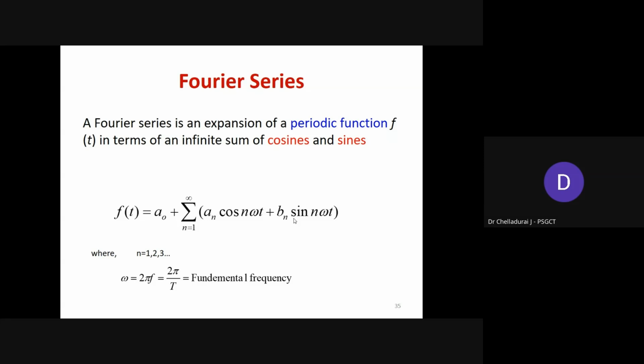So to understand further about the harmonics available in any waveform, we have to use the Fourier series method to analyze the given wave shape. By applying Fourier series techniques, it will give complete information about the given wave shape. Complete information means it will extract all the harmonics present in the given waveform.